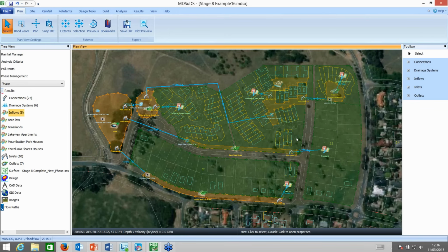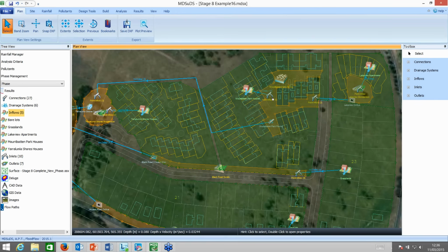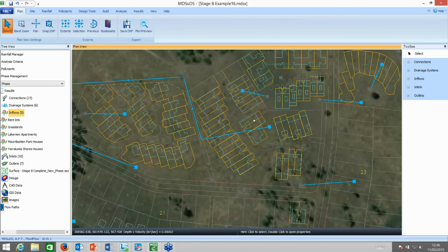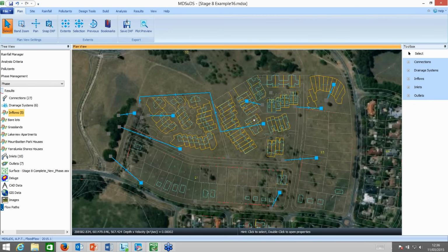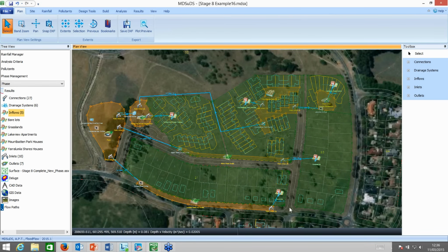particularly where we're looking at things really holistically right now, based on deluging the site, seeing where the depression areas are, and then seeing if we can massage the landscaping to suit. We're obviously not going to put a pond or bioretention area in amongst these houses and properties here. I'm not suggesting for 1 minute that you do. But where we can, maybe we could introduce things like swales, which is what we've done here down alongside the highway. And then we have got a pond where there is open space to the west of the site.